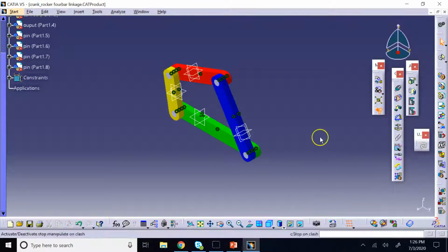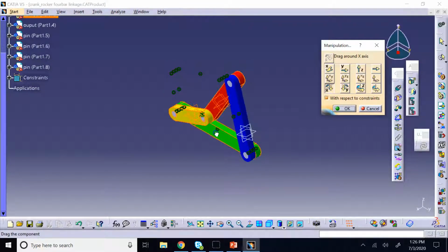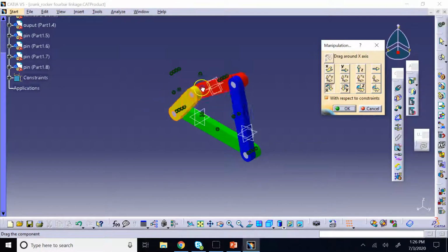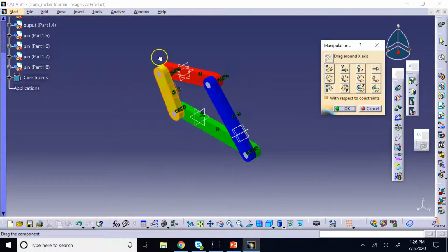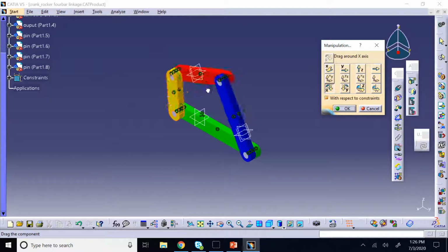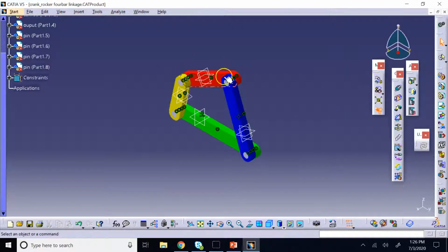So you click on that, you turn it on. Now, if I do manipulation and try to move the X member, look, hit, stop. You cannot go any further. Go back, hit, stop, right? So it gives you the dead angles, the angles beyond which you cannot move, right? So I recommend, in order to really make your assembly as realistic as possible, when you want to manipulate it, always turn this guy on, so that if there is any real physical clash happening, this one would stop it, right? So this is very important.